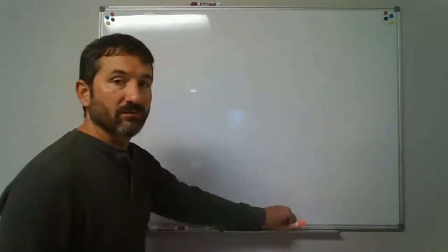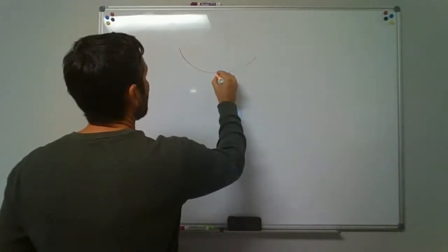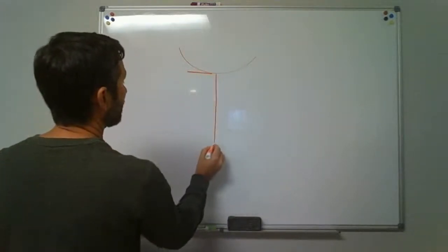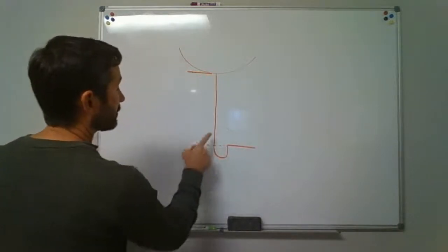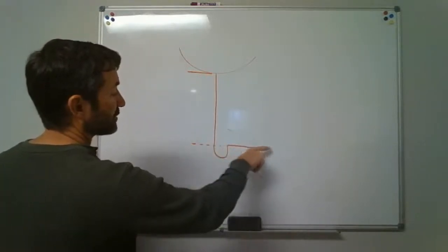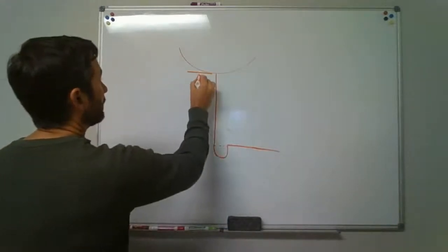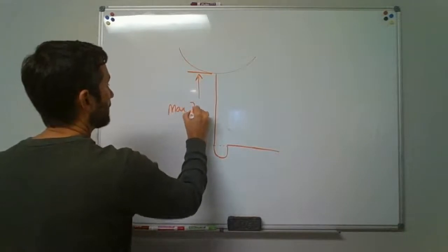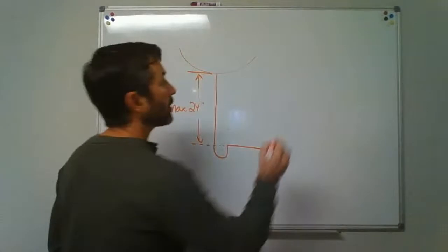So when you look at the information, it says from the outlet of a fixture, let's just say it's a lavatory sink, and you come down, we said the maximum vertical distance from the fixture outlet to the trap weir. The trap weir is right where that water is going to come out of the dip of the trap and start to run down the horizontal part. That's the trap weir. This maximum vertical distance, maximum of 24 inches. Now, that does not apply to this washer standpipe.